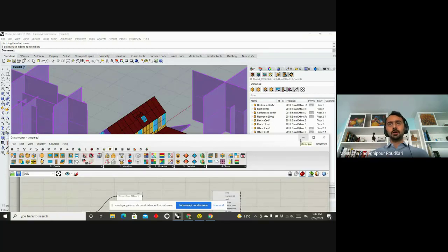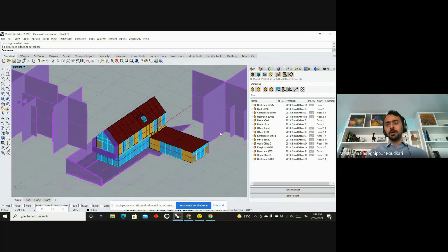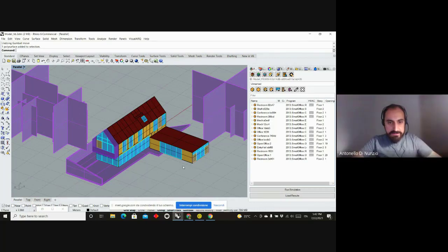But right now, yes, it will be a new room, so if it has adjacency with other faces, you have to redo it. It keeps all the information that comes from the original room, of course. Yes, the ID is different, and this is the reason why you need to solve the adjacency again. But thanks for the feedback.